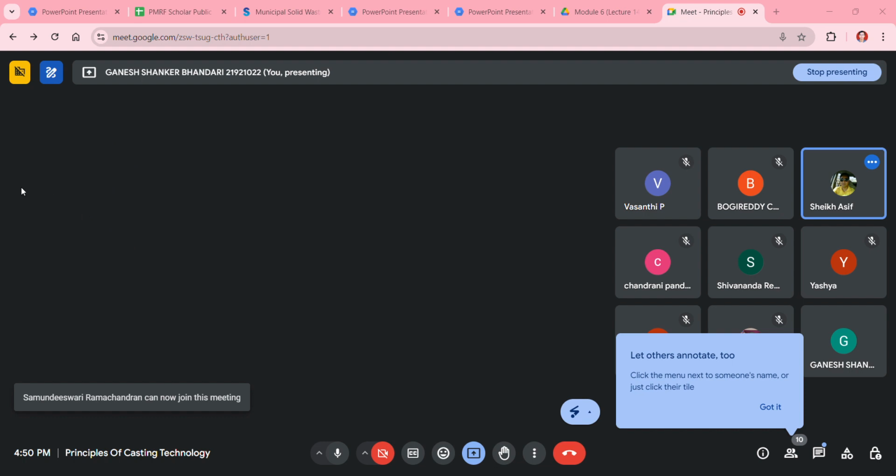We have been given the at-site time, no? Yes. The at-site time will include your container unloading time also, at the stationary site, at your transfer station. Because in the hauled container system you have to pick up that container from that point and unload it at the site. So we have been given the at-site time, that is 0.053 hour per trip. At-site time includes container unloading also.